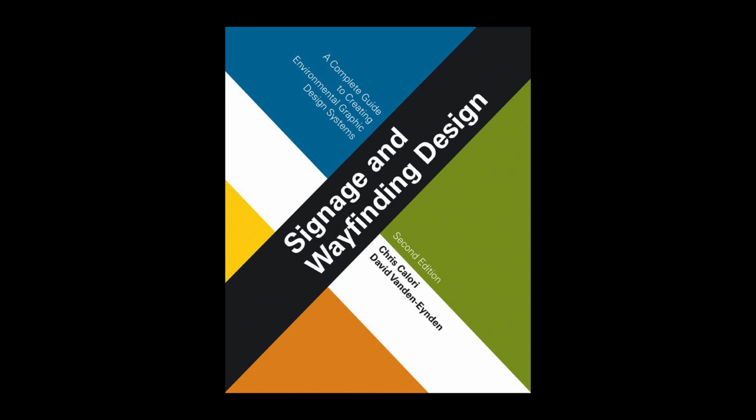Often the signage specs are wordy enough that they're easier to produce as a letter-sized word processing document than to put on the drawings. See Figure 2.30. And even if the client doesn't demand strict CSI language, the EG designers should not be surprised if they are told to label the signage technical specs as Section 10.14.00, which is the section of the CSI MasterFormat devoted to signage.